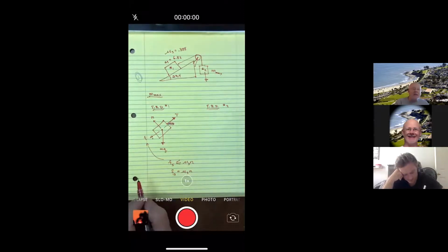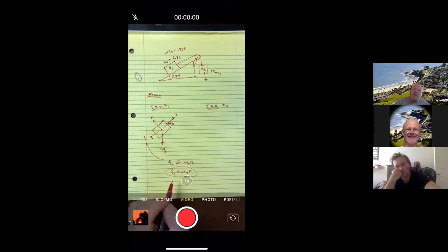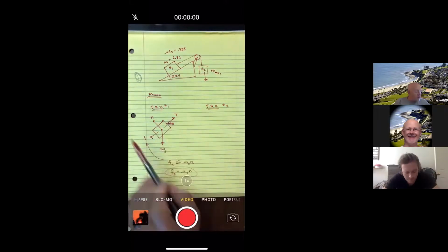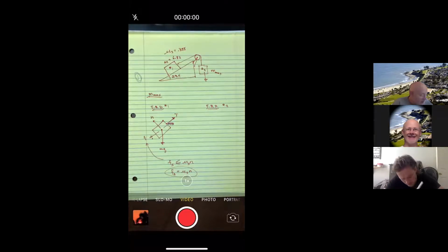And I'm going to say that a second time when we get back to the minimum weight. But I do want to point out that you've got to be careful with these static friction ones, because the static friction does not always have to be its maximum value. This does not have to be an equality sign. It does for this problem, because the problem deliberately said, what is the most weight I could hold? And the most weight you could hold up here at number 2 is when the frictional force is at its maximum. So that's why I'm going to make this very important step by changing it from an inequality to an equality as I move forward in the question. And maybe when we get some numbers at the end, I'll come back and readdress that, to help you understand that. But that's a big piece.